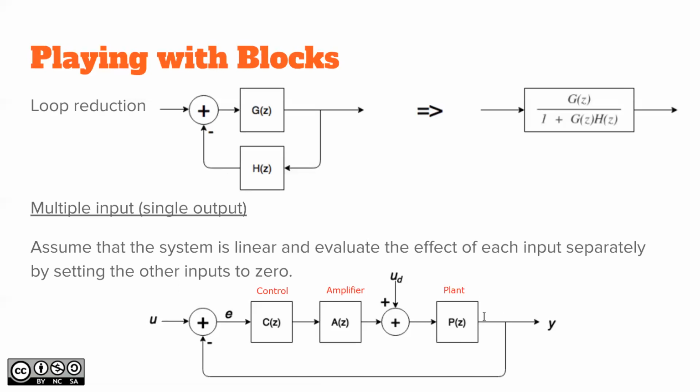So we are measuring whatever we want to control, and that one is the difference signal. This feedback loop, if it's done correctly, tries to minimize the error, meaning the difference between the RPM value we want and the controllable value, what is real.